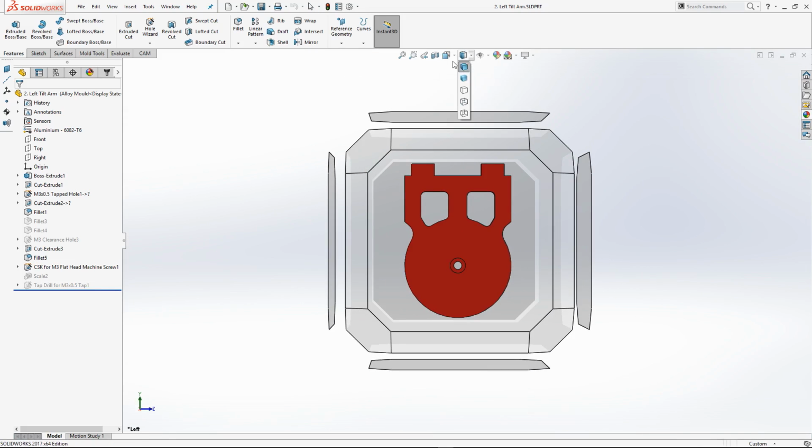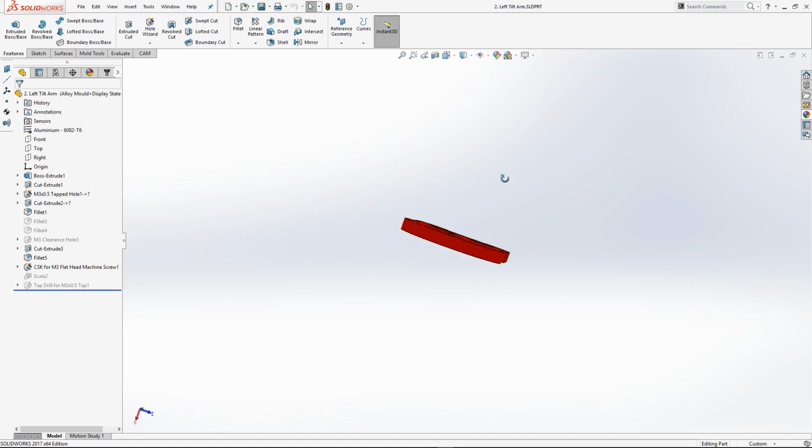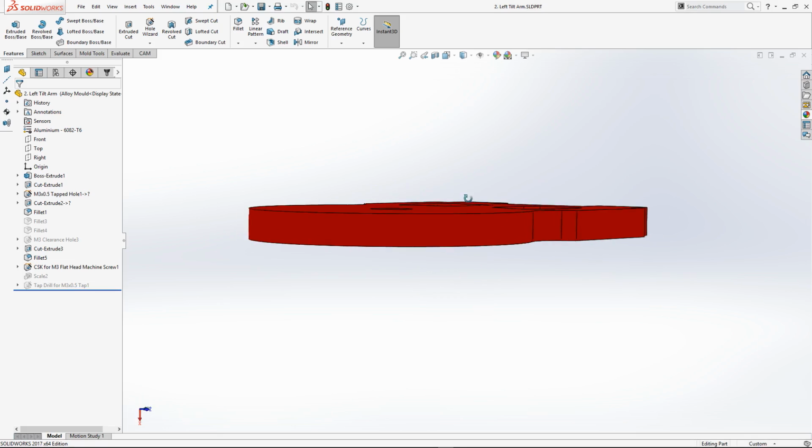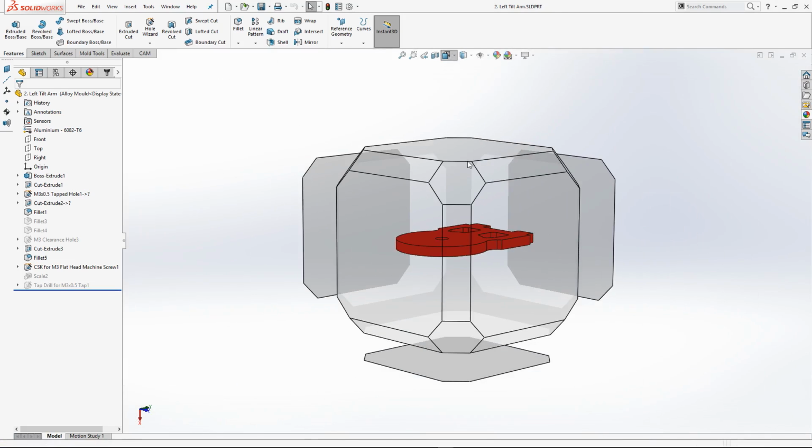Oh, apart from this one, new view. You can create a sort of customized view, so you move your model where you want it to be. So say for instance you want to be able to just pop into this view quite often, or that's a view that you want to show somebody. If you've got a customer sat behind you and you're explaining to them this is this angle for this, then you can create yourself a new view by setting that angle, going into views, click that one, type what you want to call it, click OK, and then it'll appear in your default views.